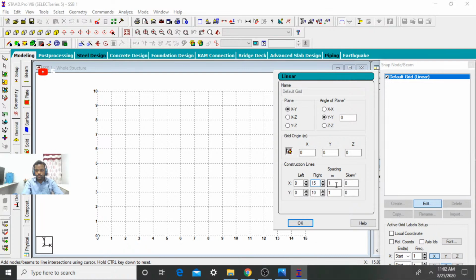After that we need to select the spacing option. If you want any 0.5 value or 0.3 value or 0.2 value, we can edit those values with the help of the spacing option. Here I am selecting 0.5 for a simple explanation. Click on OK button.